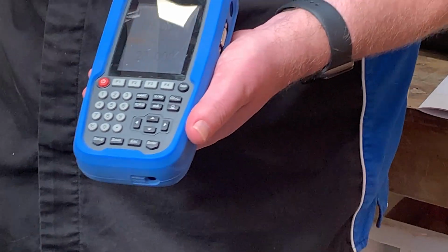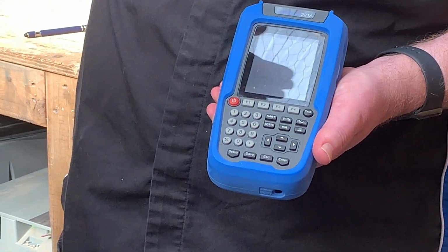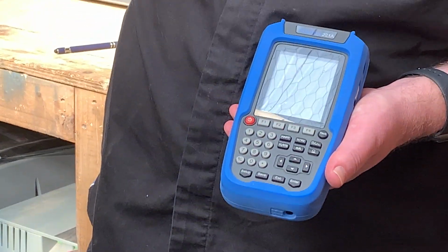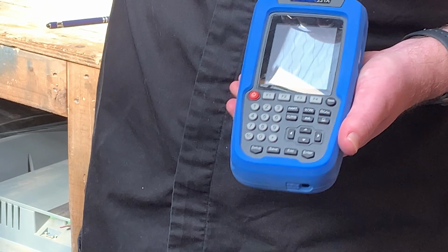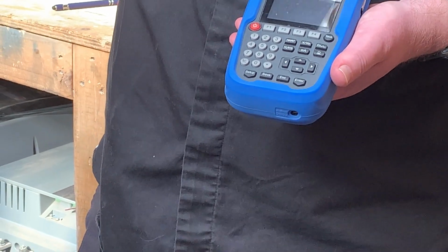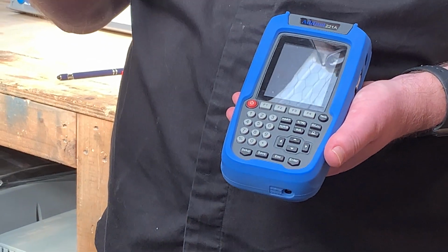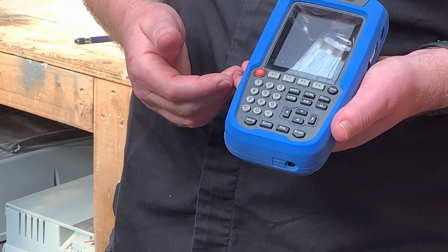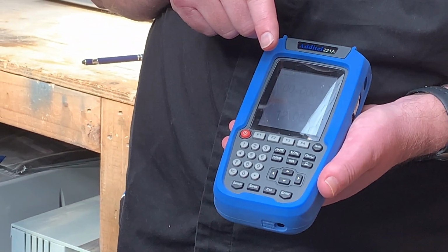Or I had this in a real case. I was at a plastics manufacturing facility and he had a Modutrol controlling gas burners and it was hunting. So I went to 12 milliamps halfway and it was hunting up and down. And I said straight away, that's your feedback potentiometer on your Modutrol. And the Sparky was like, I've been here for 2 hours trying to fix this. He was right, Peter. And again, you can do the whole ramp thing again.